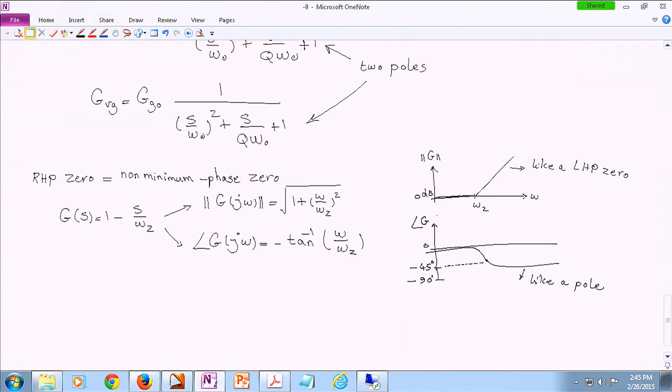And that extra phase angle induced in the system may potentially make the system unstable or may force you to be very conservative when it comes to designing the compensation network, and therefore the bandwidth should be very, very small. And we are going to see that later. I'm just basically trying to introduce the topic a little bit here.